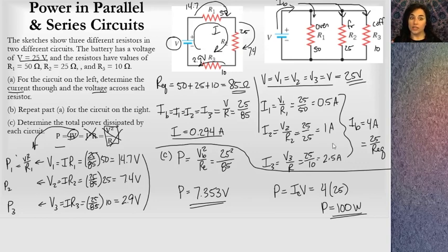And they'll each get a different current, and the circuit breaker will work when this current gets too large in here, right? This voltage will be the same the whole entire time, but as you load more and more devices onto the circuit, the current's going to keep going up and up and up, okay? So that will increase the power through your circuit, but the current will get too high, and that is a hazard to have too high of a current. So that's why they put circuit breakers on a circuit like this, is because you don't want the current going too high.